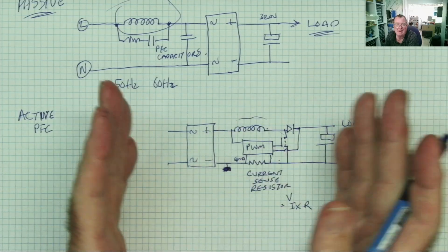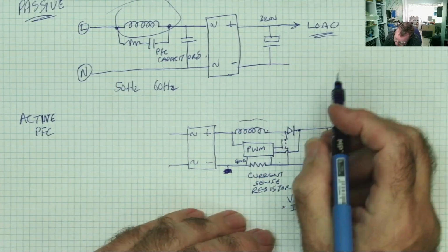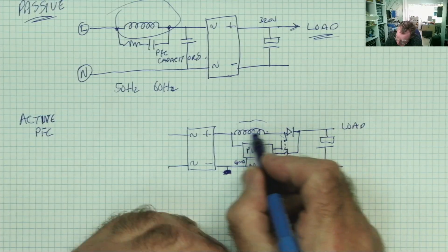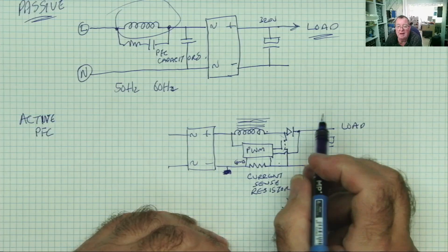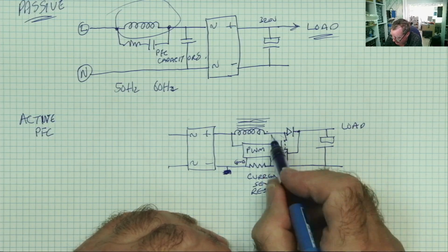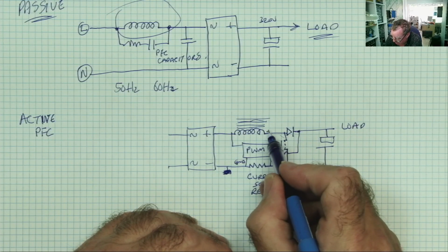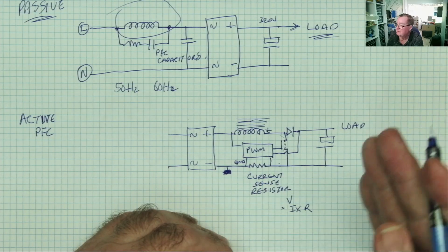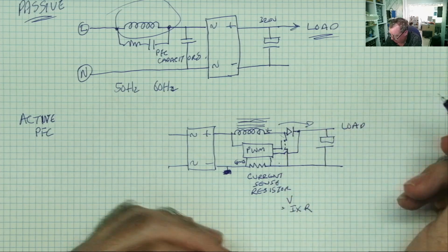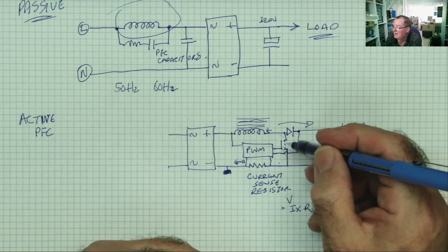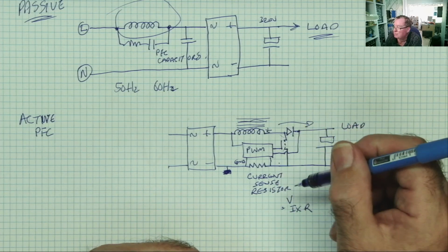Again, we'll get this 90-degree shift, okay? And before this coil can fully magnetize, it magnetizes with the current. This is switching back off again. The coil now demagnetizes, and the voltage at this end of the coil increases, and that goes through the diode and charges the capacitor.